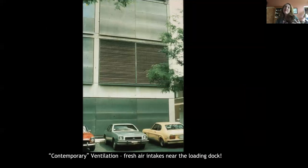Now today, the notion of providing fresh air in a building is typically just an afterthought. A building has to have fresh air intake. It's like the building is breathing. But oftentimes they want to hide those grills. So where do they put them? They put them in the back of the building, next to the loading docks, by the parking lot, because they want to hide them. But that means you might have all of these cars and trucks that are idling. So just because it's outdoor air doesn't necessarily mean that it's fresh air.